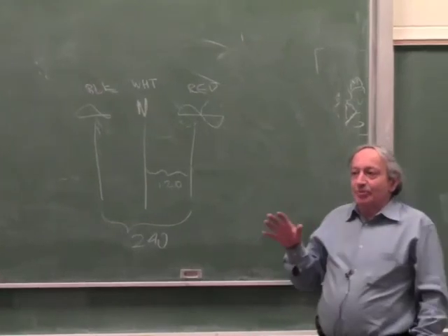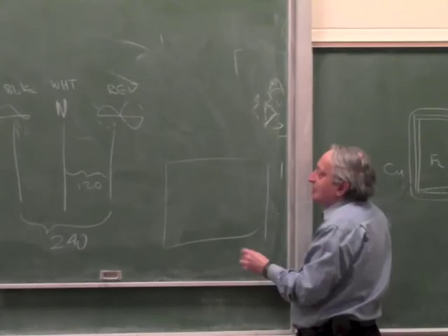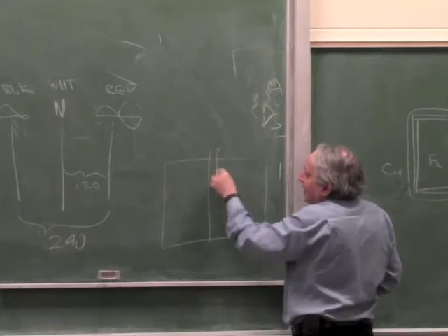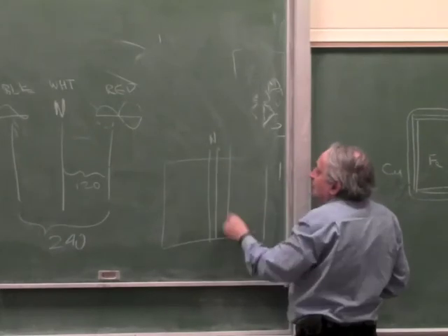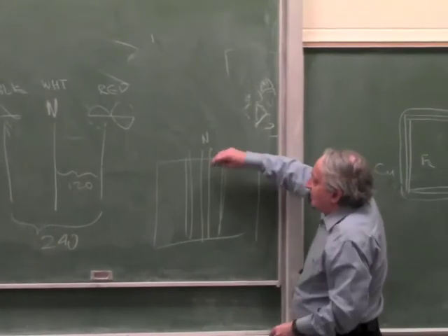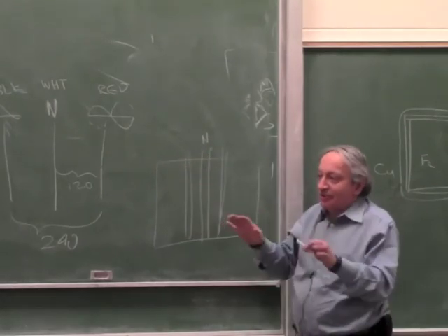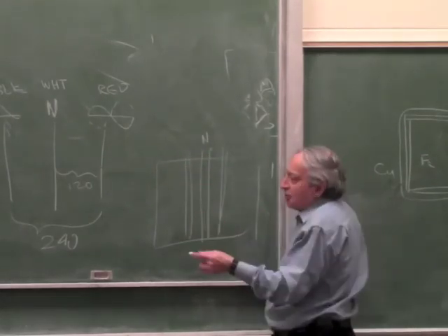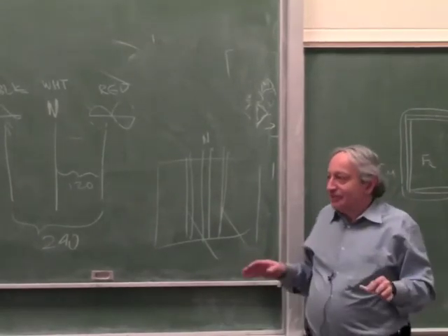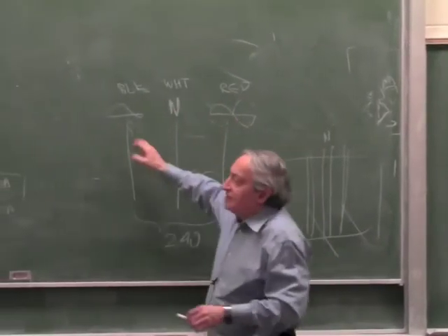And that's how all the breaker boxes work. If you look inside the breaker box in a house, you have two phases, and in the middle you have a bar, which is the neutral. The breakers take it alternately. The first breaker takes neutral to one phase, the second breaker takes neutral to the other phase, to load both equally. If you want 240, like for a kitchen or a dryer, you take it from the two opposing phases.